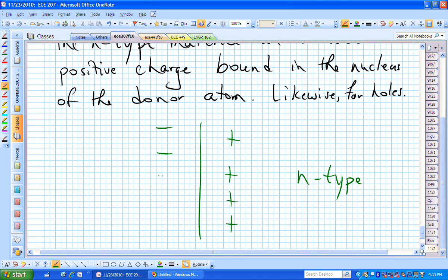Here is the electron charge that's bound in those elements on the left in the p-type material. And anytime we have charge separation, we have a field. We now have this electric field that conventionally is from positive to negative. That's now our E field, or our electric field.